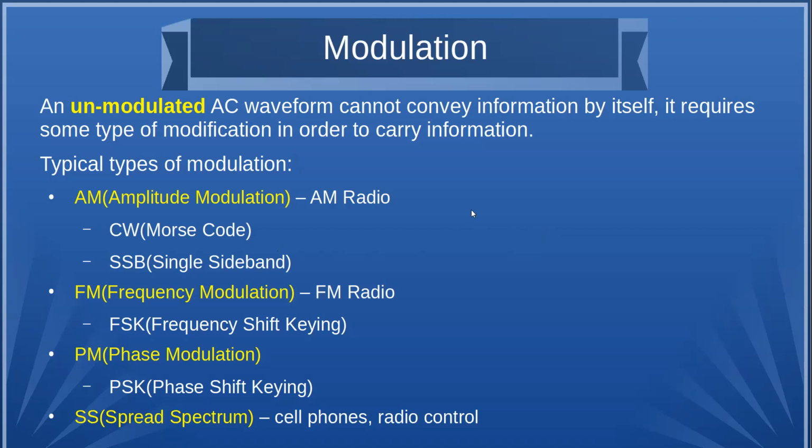To do single sideband, you eliminate the carrier and you eliminate one of those sidebands. So you're only going to transmit the baseband signal shifted up in frequency. So you have more power in that small amount of the waveform, because you're not using power to generate the carrier or the lower sideband, which is a duplicate. It's just reverse frequency. It's a mirror image.